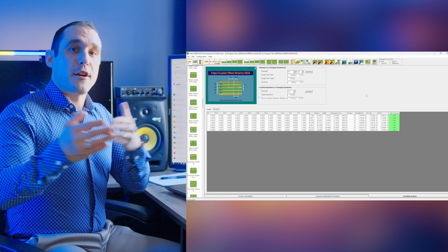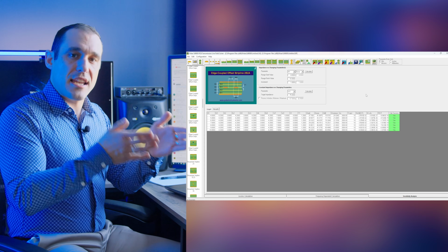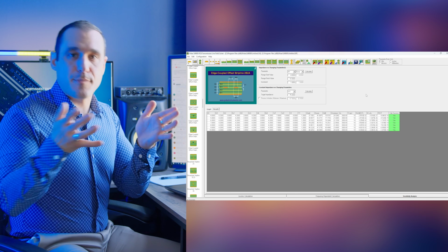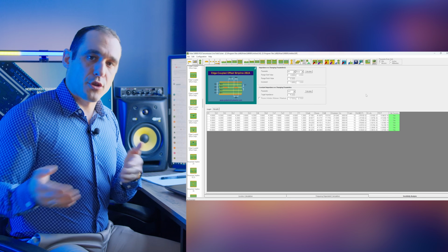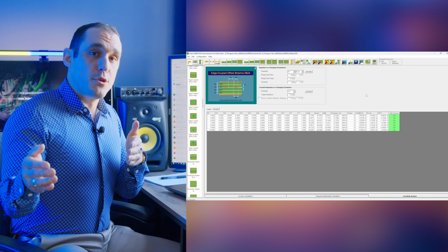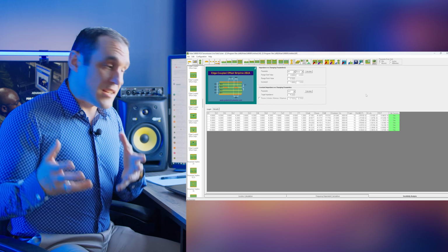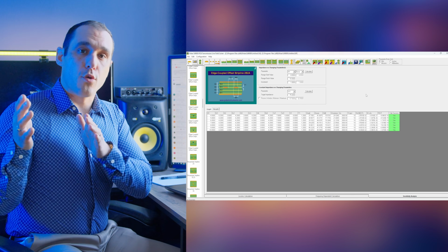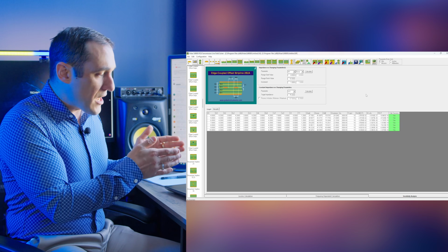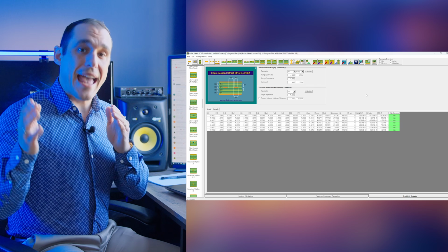You can then, of course, vary the stack up or vary things in the transmission line model like the spacing or like the trace width. And you can then resimulate and see exactly what the crosstalk is going to be. Again, this is really useful for estimating the routing density that you're going to use in your design, because you need to figure that out in order to set your clearance constraints when you actually get into your CAD software.